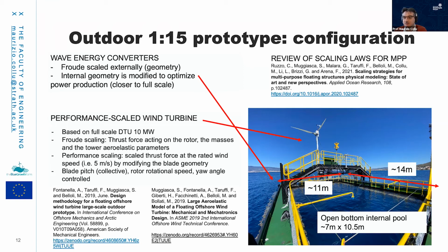For the wave energy converters, again, one of the main aims of this platform was to be able to validate our model. Our model is focused on verifying that all the conditions are right for this platform to operate. Externally, the wave energy converters are being scaled according to Froude and geometrically, but internally, for those of you familiar with oscillating water columns, you know very well that the pneumatic behavior of the air within the chamber is key to modeling the power production. So internally, there is a different scaling approach in order to make sure that power production is optimized and closer to the full-scale concept.